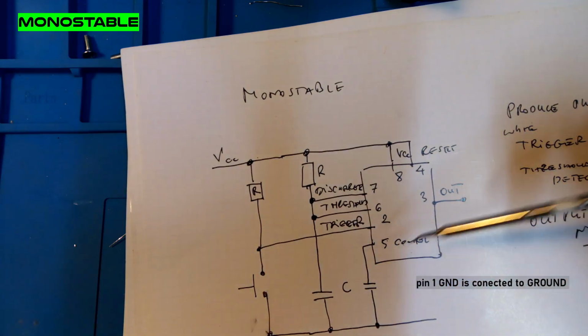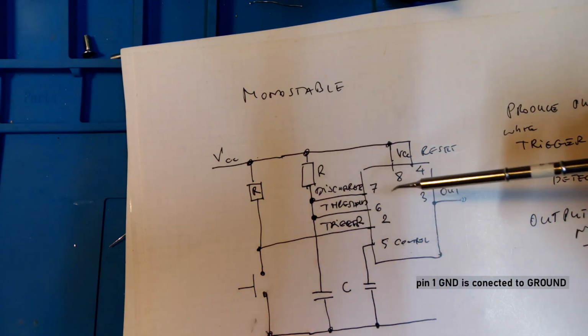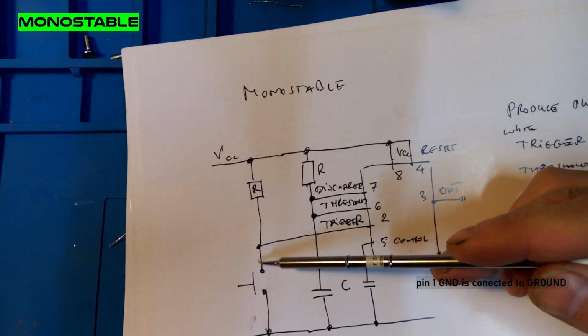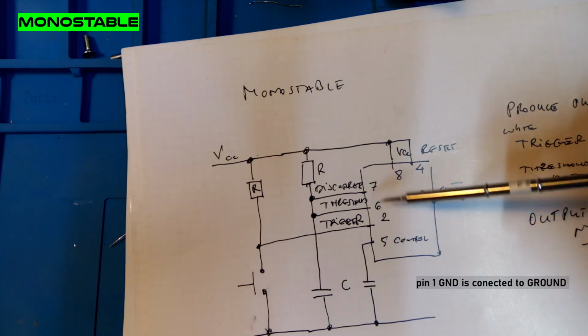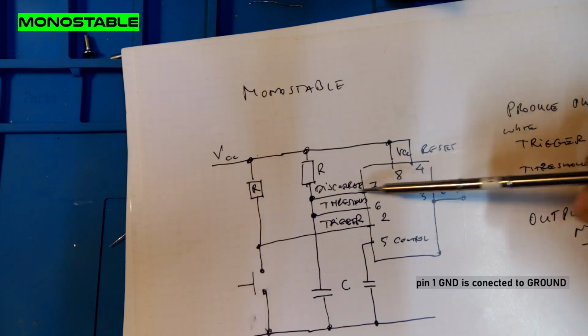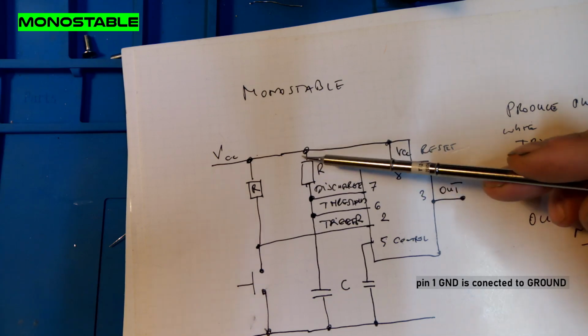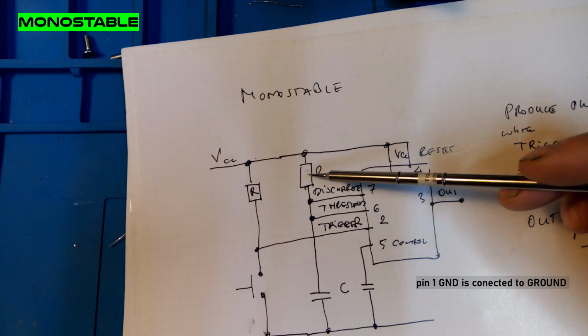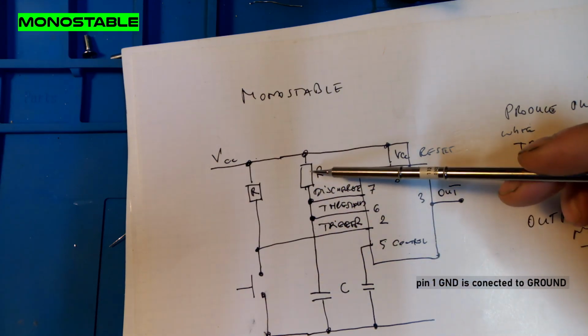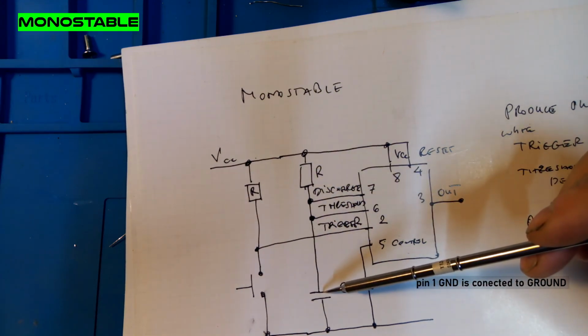Forget about it; it also sometimes works without it. We have a switch for triggering. Threshold and discharge are connected together, and the brain of this wiring is this resistor and this capacitor.